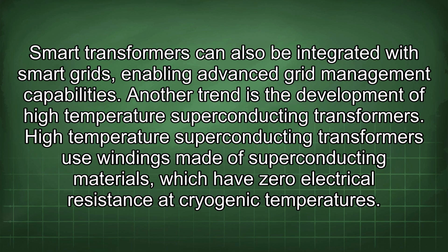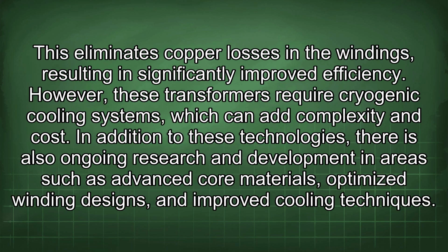Another trend is the development of high-temperature superconducting transformers. High-temperature superconducting transformers use windings made of superconducting materials, which have zero electrical resistance at cryogenic temperatures. This eliminates copper losses in the windings, resulting in significantly improved efficiency. However, these transformers require cryogenic cooling systems, which can add complexity and cost.